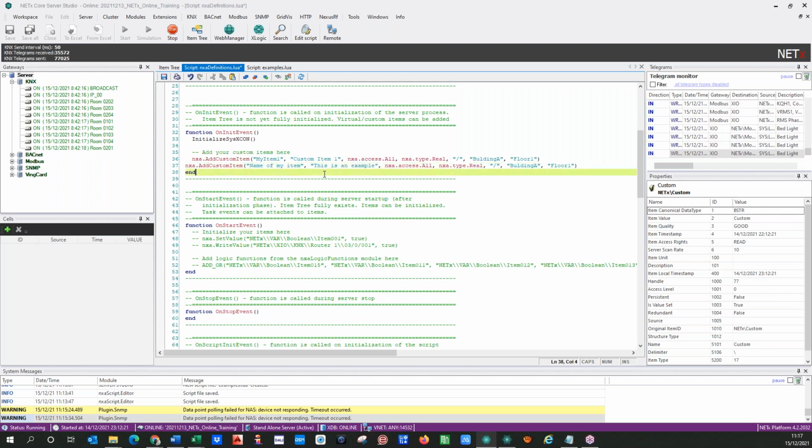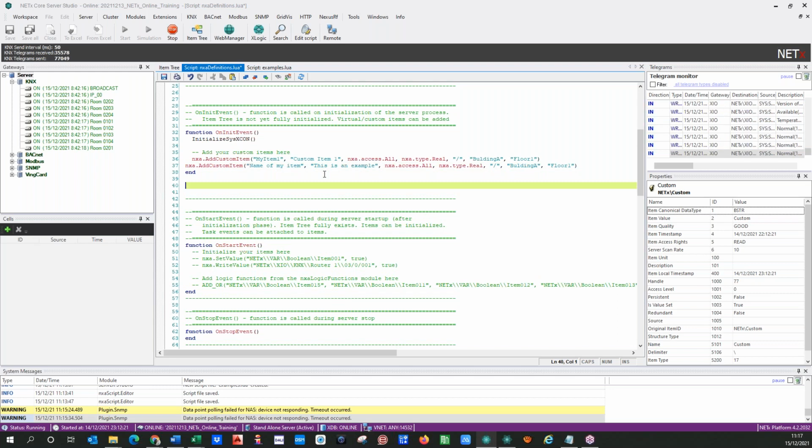Look, if I show you this here. If you press the buttons Control and space, you trigger a list of options that you can write here. That's fantastic. Control and space. So you see all the functions that you have here in the Lua engine. A lot of them are NXA, but some of them are not specific for NetX Automation, they are to manage IO information, files, or math operations or whatever. There are a lot of possibilities.